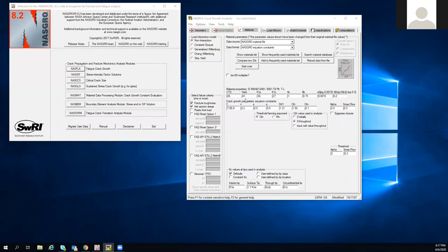And there are other cases that may be used to change that. For example, if these are the minimum values, but you know from the certificate of conformance that comes from the metal houses that maybe the minimum yield strength is actually something like 43, and that's been confirmed from test data, you can change those as well. So, you're free to change these, but just be aware that making those changes is going to deviate from the test data that has been calculated from actual ASTM tests.